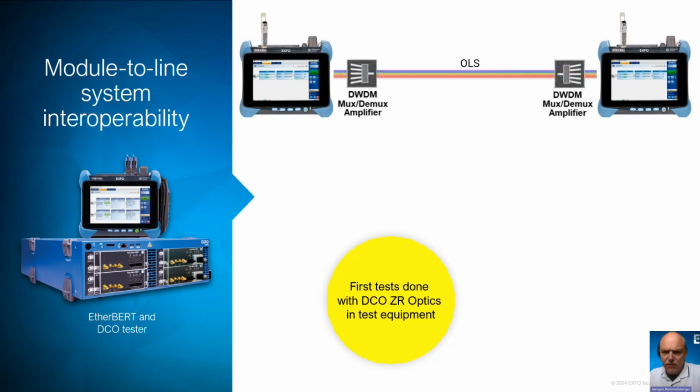So for most cases, we only need to verify and test that the BER is less than the predefined threshold, which means the number of bits required to accomplish this will only depend on the required confidence level and the BER threshold. And the confidence level here is the percentage of the tests that the system's true BER, the bit error rate, is less than the specified bit error rate.